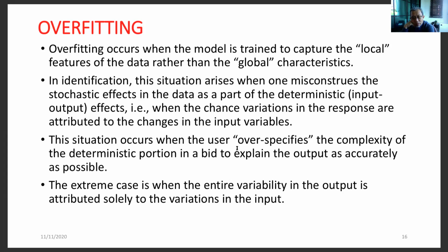So when the system is third order, the data is captured from a third-order system. Okay, the real system is third order. Sometimes we fit the third-order system with a very high-order model, for example, power of 6, power of 7. It means the higher order actually didn't fit. It's not the best solution for the system ID. In a matter of fact, the 7th order or 6th order can be simplified, and this occurs due to the fact that the system has been overfitted.